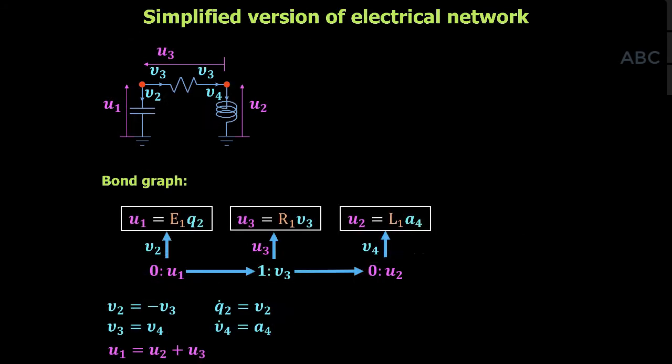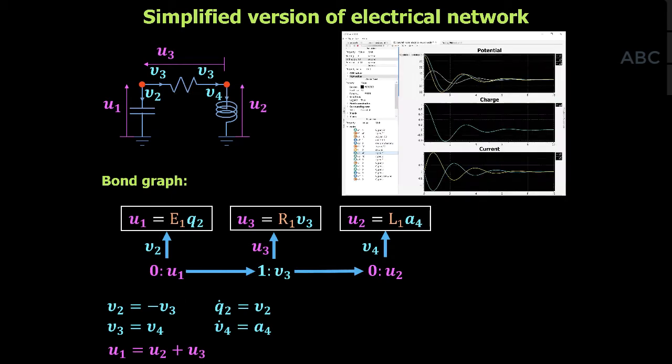So if we do a slightly simplified version of this to solve it, we just say that we've got an initial charge on the capacitor, and then put it into CellML form and solve it. You get what you'd expect in terms of dissipation. You're exchanging energy between the capacitor and the inductor and dissipating it through the resistor. So there are two other concepts that become critical when you're dealing with energy movement between different physical systems.